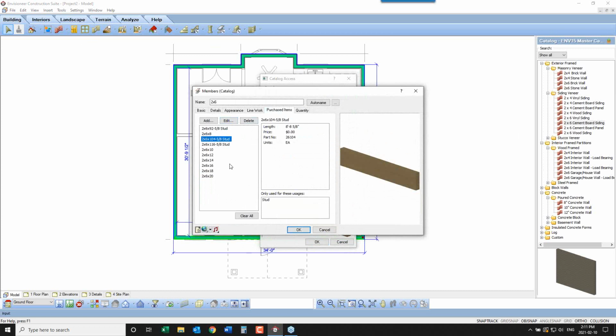It knows those heights, and it has them published here, the length of that board, so it knows to use them. And each one of these boards has rules set to it as well. So when I'm looking at these pre-cut studs, look down here, only used for studs. This 10-foot board cannot be used for blocking or plate material. Don't send any 10-foot boards out for plate material. Send a mix of 12s, 14s, and 16s. When I come to an 18-foot board, don't use it for blocking, header, sill, or plate material.